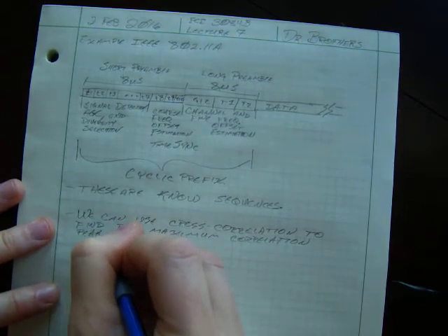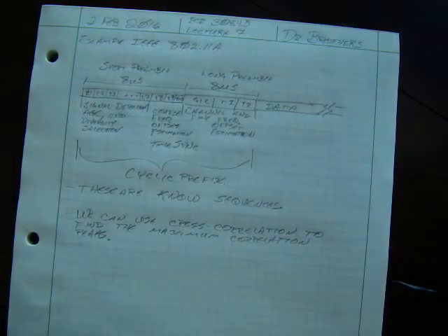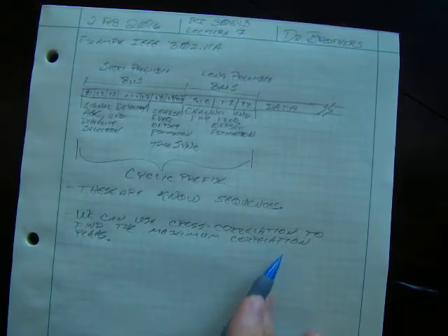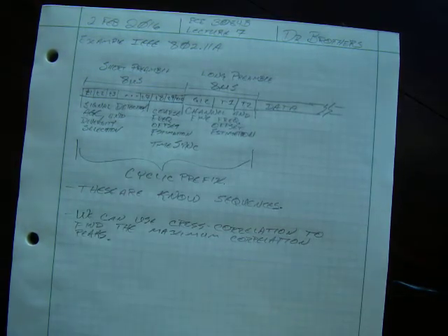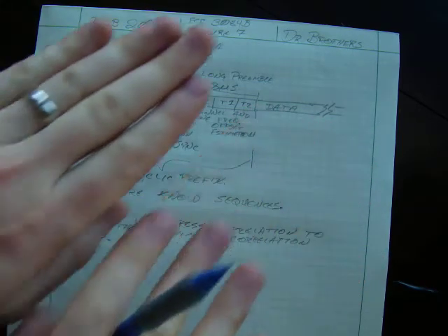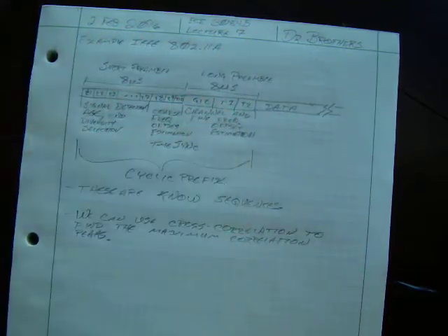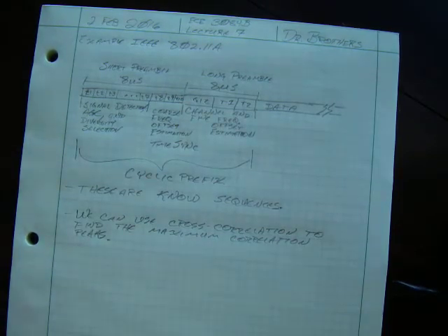Now, we were talking in class about autocorrelation, and we said that in autocorrelation, when it has the maximum correlation, that means that T naught is equal to 0. So that's really what we're trying to find here: where do these two waveforms sync up, and they will correlate up to the maximum value. That maximum value then gives you the synchronization pulse to have everything come together.